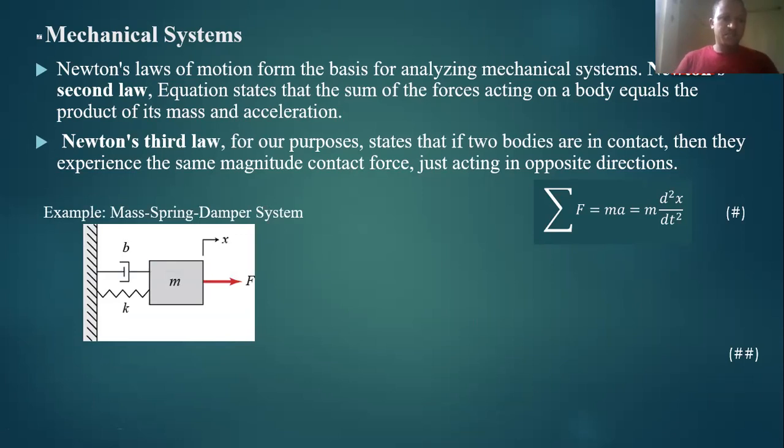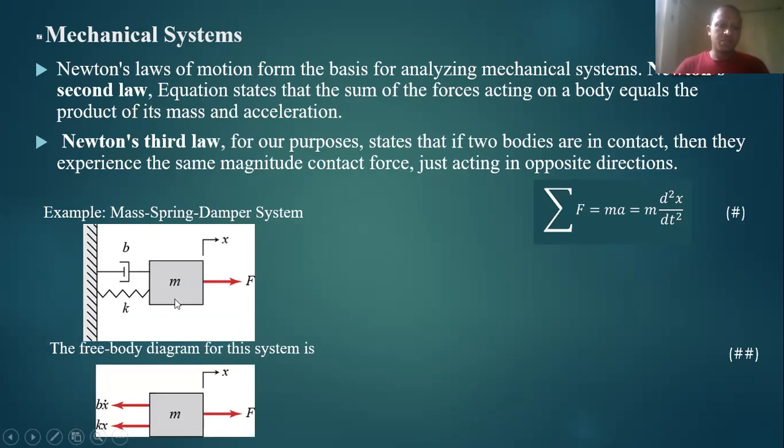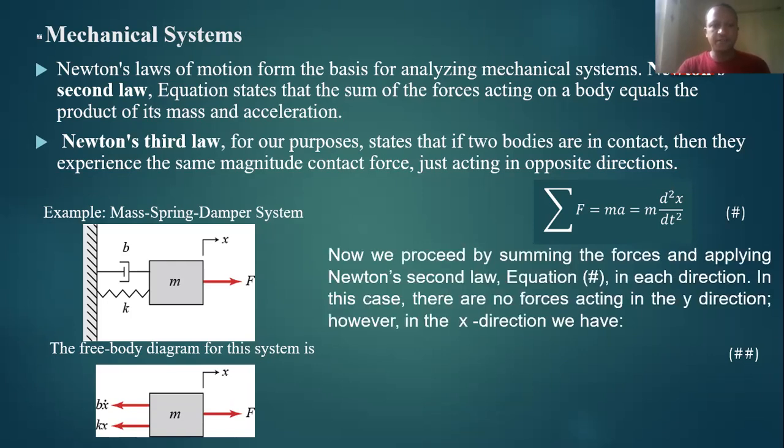So this is the figure, a spring mass system also having a damper here. This is a spring mass damper system. We can produce a free body diagram for the system, considering what will happen on the links of the damper and the spring when we apply force on it. The spring is a representation of material stiffness here. It is not simply a spring, but a material representation, that is, the stiffness of the material.